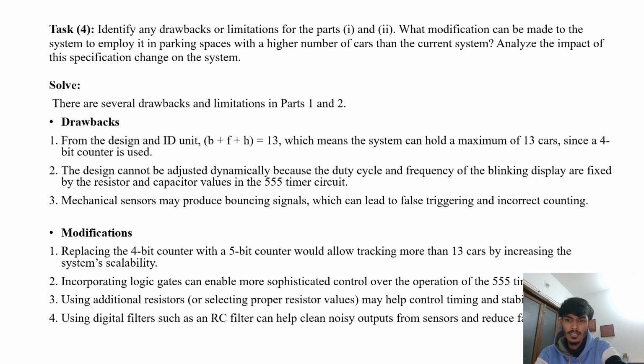Now for limitations, the biggest issue is scalability. A 4-bit counter limits us to 15 counts, so our system max is 13 cars. Also, sensors may bounce and cause incorrect counting, and the blink timing is fixed by hardware components.